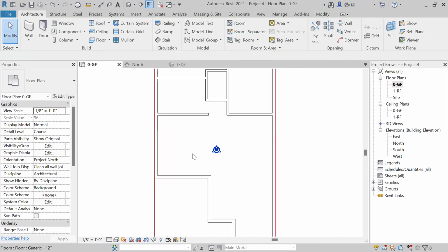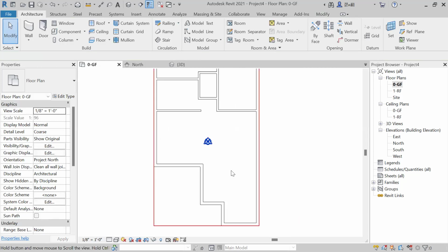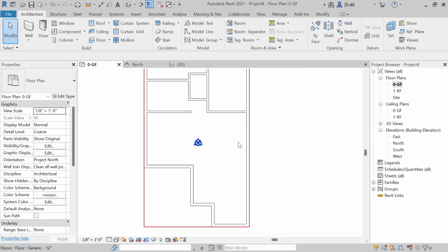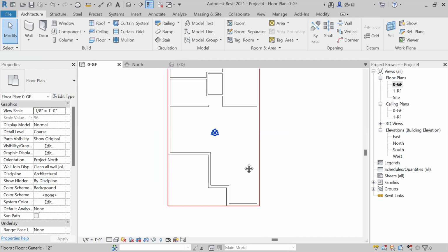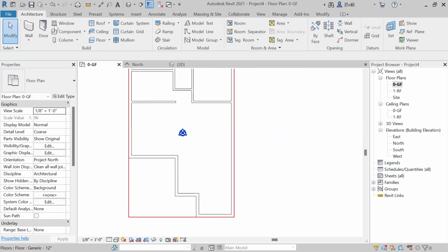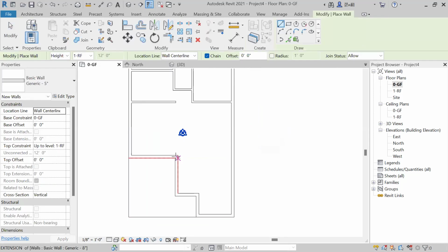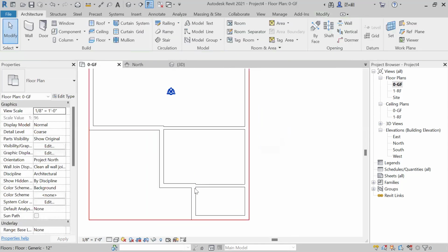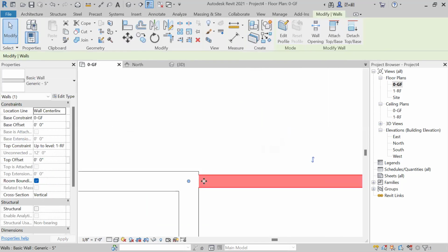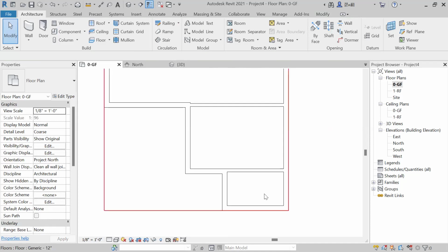Now, same way, here we have a porch. This is our main door. Here we have to place the main door. Suppose here I want to draw the staircase, if you want to go to the roof floor. So here I will draw the staircase. Suppose one bedroom I am drawing here. Okay. So selecting the same, right click, create similar. Just draw, suppose this is my one bedroom. And here I have drawn an attached toilet. Suppose inside the bedroom only, we have drawn the toilet. Just move it a little bit. Clear? This is our toilet area.